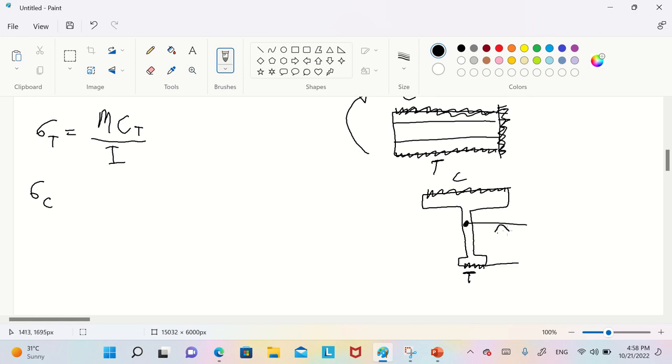This one is the 119.4 millimeter. So for the center of the tension is this, the 119.4 millimeter. Why? Because the center of the whole thing to the maximum tension is 119.4 millimeter. So we put here, we have a moment 15 times 10 power 3.